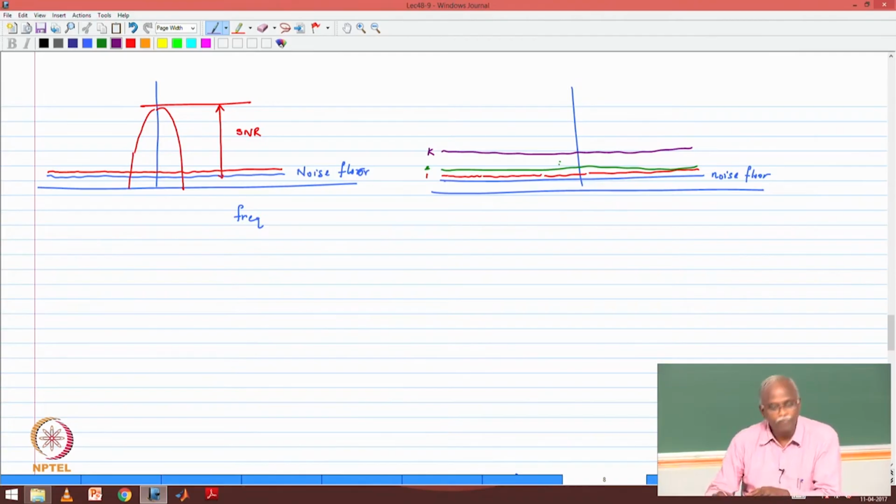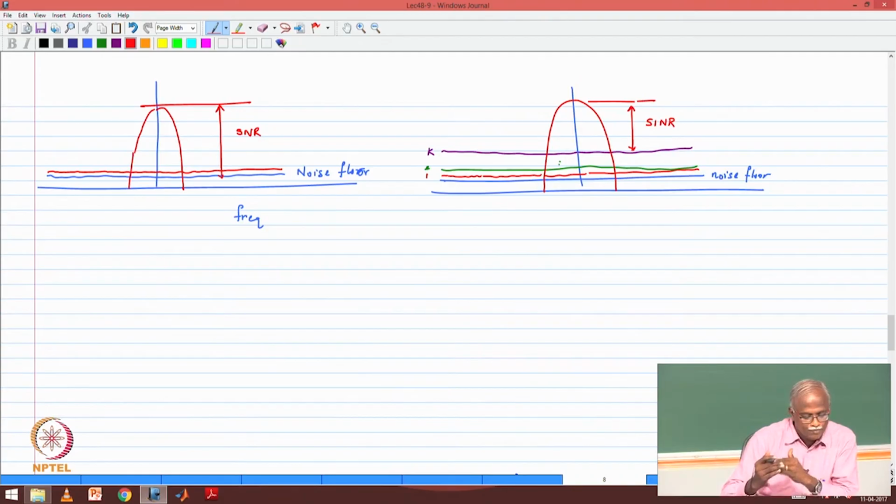Okay. Now if I detect red user number 1, like before, I despread my signal, others are not affected as part of the despreading process. Notice something has happened, some change has happened with respect to the previous figure. My threshold or difference with respect to the impairment is now no longer SNR, it is SINR, and it has become smaller.